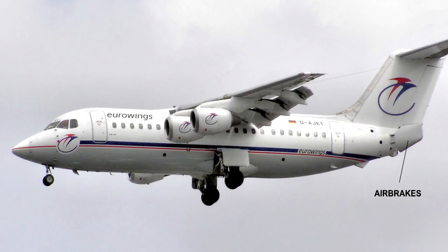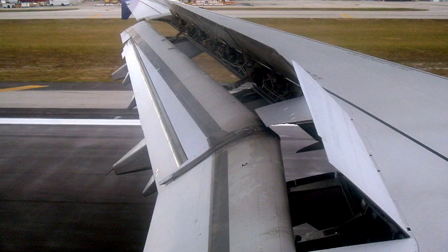Air brakes are designed to increase drag, while making little or no change to lift, while spoilers greatly reduce lift, while making only a moderate increase in drag. However, most aircraft only have spoilers. They form part of a speed brake system which can be used to slow the aircraft down in flight and on the ground. When operated, they reduce the lift on the wing. Thus, in order to maintain altitude, the aircraft has to be pitched up, increasing drag and reducing airspeed.